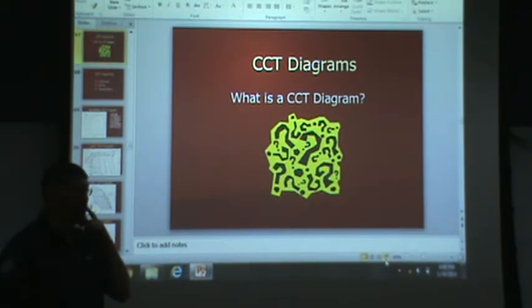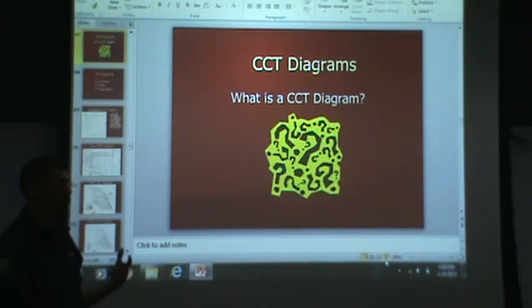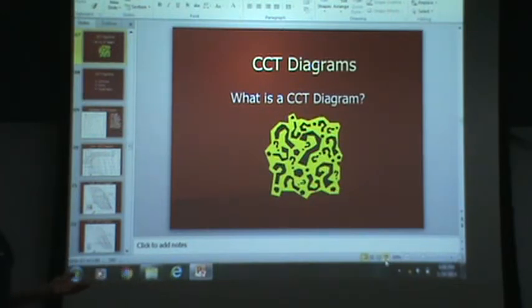I was telling the students before you got in here that we have a situation we're dealing with right now where we model the job mostly because we were trying to do stress analysis so that we didn't have cracked parts. And the model didn't show any dangerous stresses, so we went ahead and did heat treatment, and parts went out without further machining by us. The customer got them and they found that there were lots of cracks in the parts. So the models are only as good as the inputs, and every situation we deal with is unique.